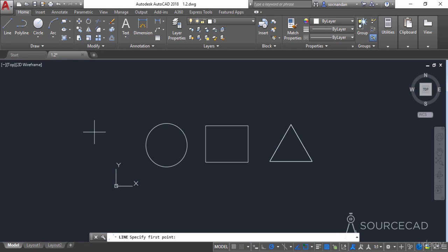So simply go to that command and left click, and the command will now be activated. Once the command is active, you'll notice that its name and also the instruction will be visible on the command line, and the cursor will change into a point selection cursor or a pick box. In order to exit this, simply press the escape key. You can press escape multiple times also if you want, so that will not make any change to the drawing.